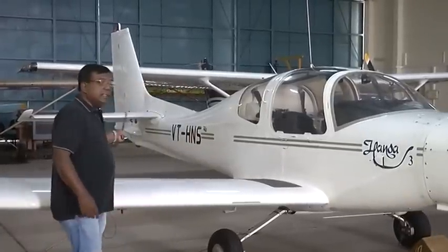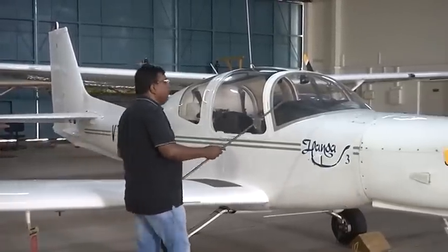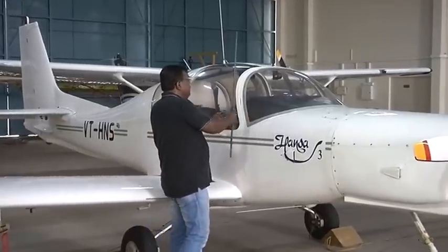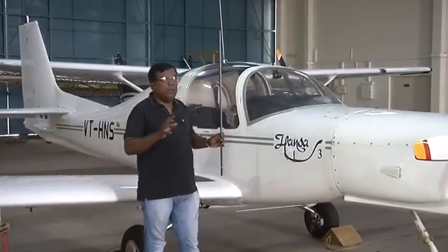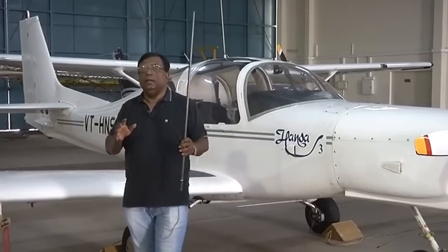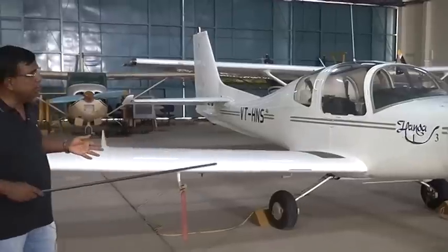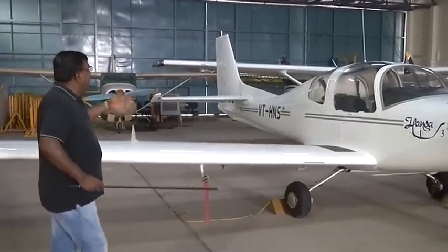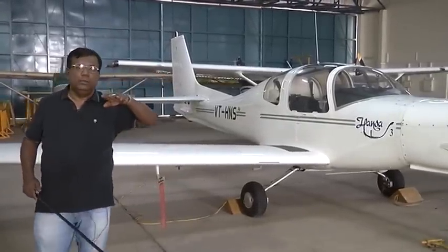Similarly, from the horizontal tail, all those forces which were acting at different points of location, I am transferring them to CG with force and moment. So now, when I apply the point mass model, I have an assumption that all these moments are balanced. And in practice, how are they balanced? They are balanced by design, by a configuration design. And in addition, you can use elevator, trimmer, etc., to make all those moments balanced.